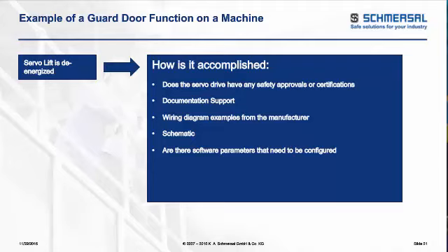So you may need to take down the three-phase power to the drive. Again, easy to say, not always easy to implement. You may have additional considerations, where you may have to break the enable or the inhibit signal to the drive, creating a safer condition by using the dynamic braking function of the drive to get the motor to stop as quickly as possible, and then use a time delay to break the main power, because many drives do not like seeing their power lost when the motor's in motion.